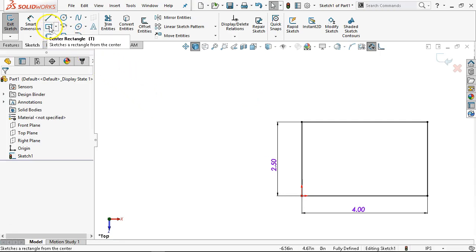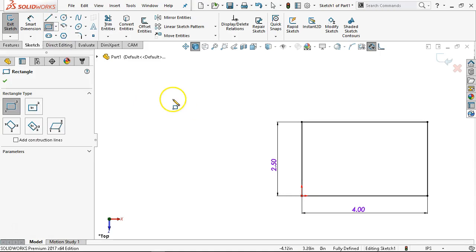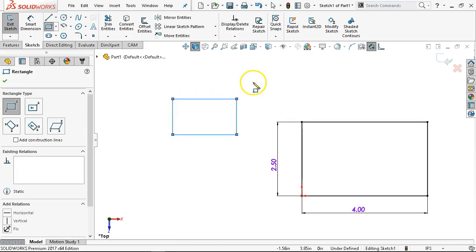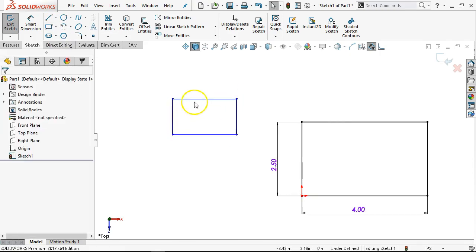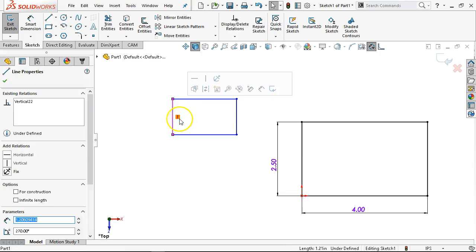Okay, let's go back to the corner rectangle. And we can either highlight it, and on the existing relations you can right click and delete, or when you see the little green boxes, green box says I'm showing you the relation for that object. I'm hovering over it, so it's orange, and it's highlighting the object in magenta, saying these two are connected.